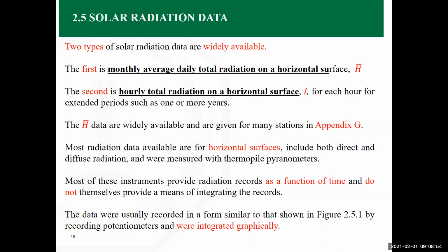Now things are much easier. We can run an experiment in any location and get the information that we want locally. For example, you can put a pyranometer there, get thermocouples to measure the temperature, and get instrumentation for measuring the humidity of the location. You can also measure the wind speed, which means you can do your own calculations. But this is only for the period you are running your experiments. If you need the information for an extended period, then you need to go to sources.